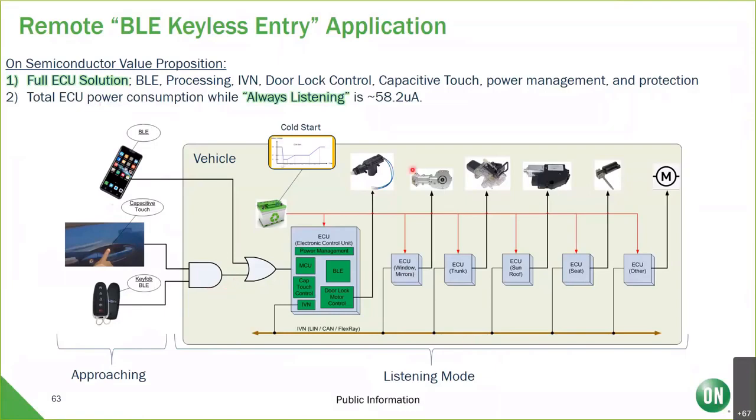So this device, this ECU here, is always listening, right? It can't burn a lot of current because it's always listening, because you're away. So this solution that I came up with is 58 microamps of always listening current.